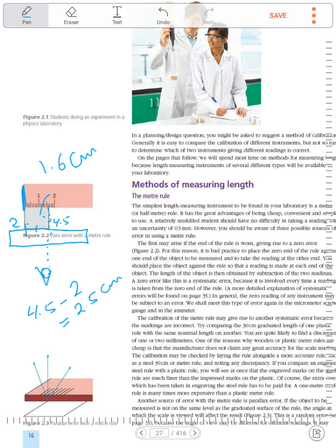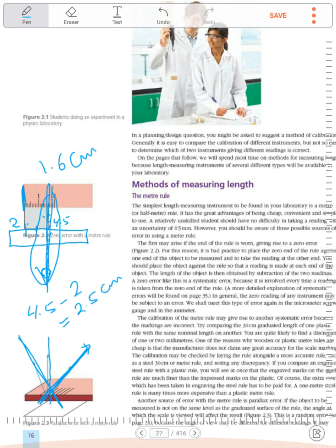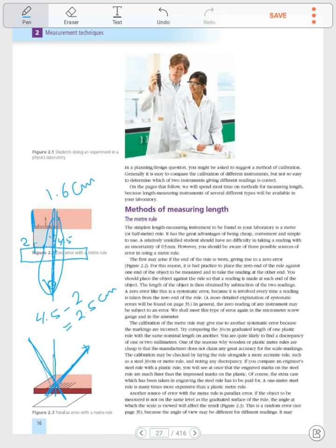So you have to look perpendicularly to avoid line of sight error or parallax error. That's your eye, the reading, and the object on the same line, okay? On the same line. If you look from another place, like here, if you are not perpendicular to the reading, you may have another value which is wrong, or from the other side. So the reading is larger or smaller than the real value. You have to check zero error all the time to check that your ruler is truly right, okay?